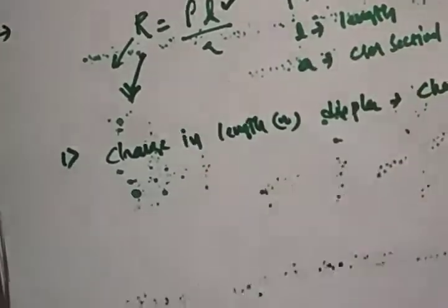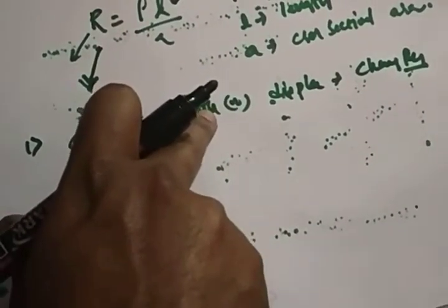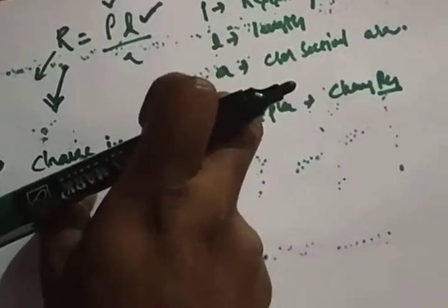So we'll get changing resistance, right? You will get the change in resistance, that is nothing but a transducer. When the resistance changes, you can put a voltmeter and find the voltage. Why did that voltage come? You are changing the displacement. So that displacement is equal to that voltage. That means my non-electrical quantity is converted to an electrical quantity.